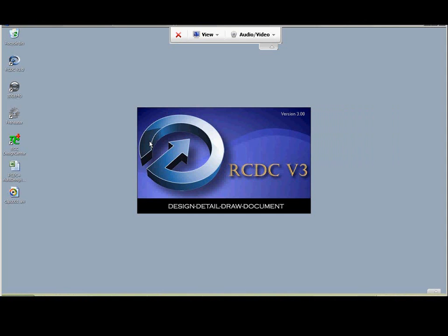The RCDC can design and detail beams, columns, shear walls, open footings and slabs. It can link to a STAAD or an ETABS file. As long as the analysis is done in either of these analysis engines, the software can import the analysis output, be it forces, member sizes, etc., and take it through to design, detailing, drawing, documentation, quantification, the entire stretch.